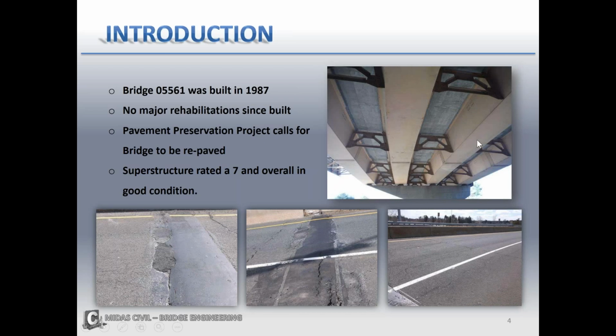Here on the top right, you can see a picture of the underside of deck, and on the bottom you can see the deck deterioration. I just want to point out in particular the map cracking and the joint deterioration, which is what the repaving was done for.